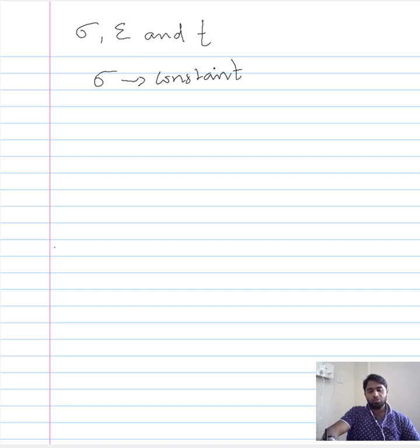It is important to note that this mechanical condition should not vary through the period of testing. Even though there might be a change in the dimension of the material during testing, the stress that we impose should not vary all through the testing. So appropriately we have to ensure that the stress that we impose is constant.